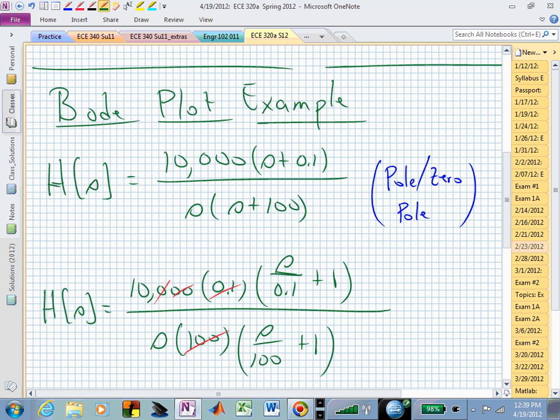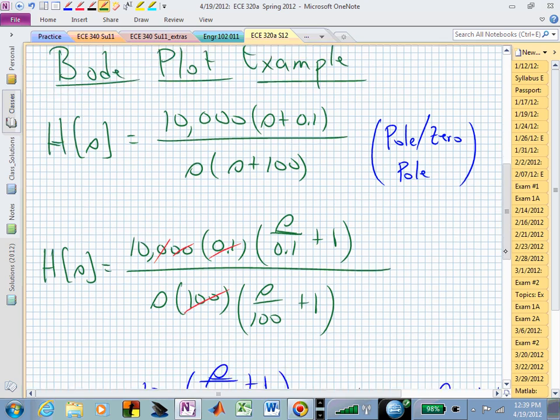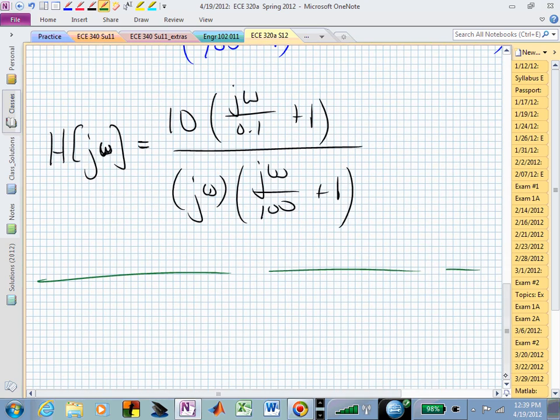You are looking at the poles of s times H of s. That s cancels that pole at the origin. So as long as you just have that one pole at the origin, H of s is well behaved, and you can apply the final value theorem to this particular problem. That's not associated with the Bode plot, but that's something that you need to know by the final.